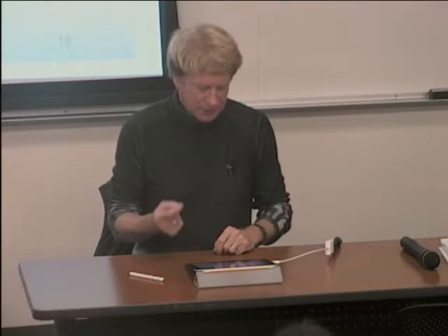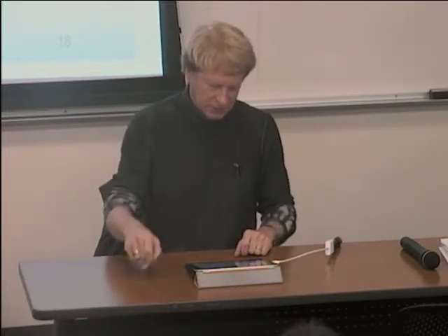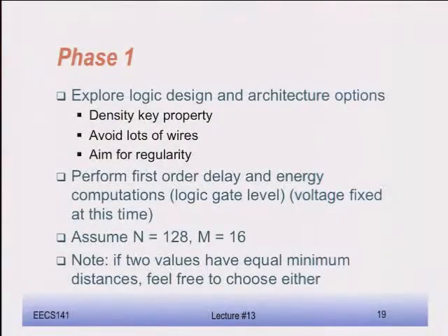As I said, what we're going to look at primarily in this round is logical design, basic functionality, maybe some thinking about how to make it a bit faster, and then logical effort sizing of your devices in such a way that you minimize the delay. Okay? So, key roles: explore logic design and architectural options.